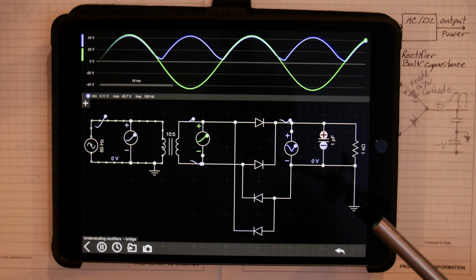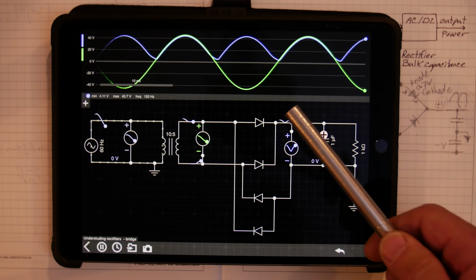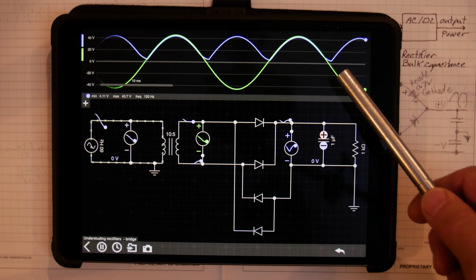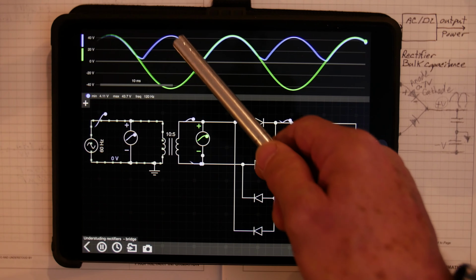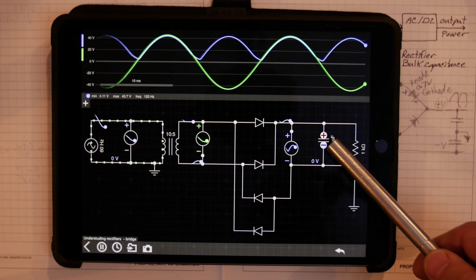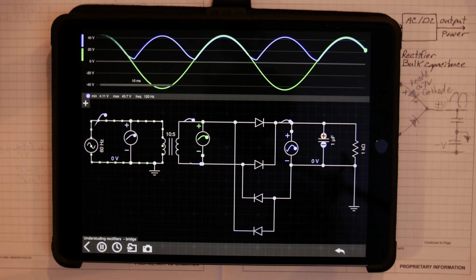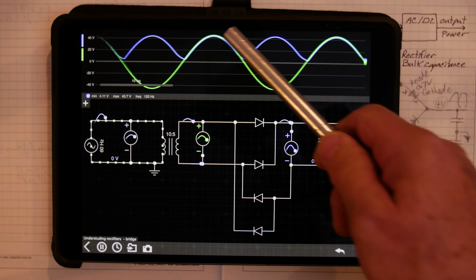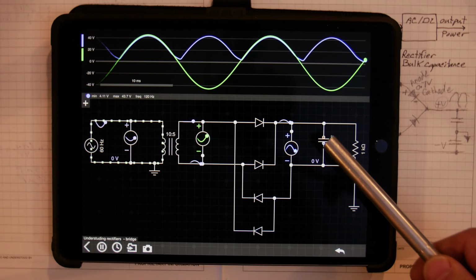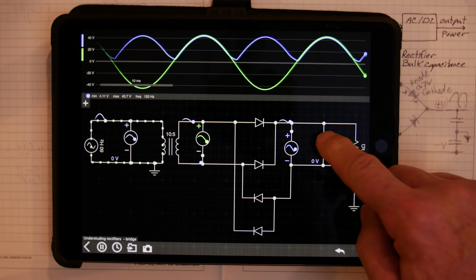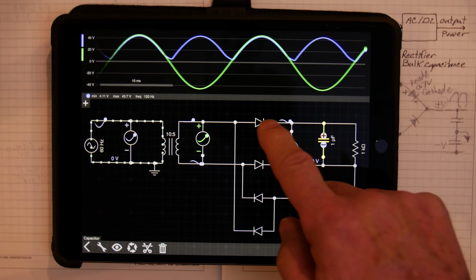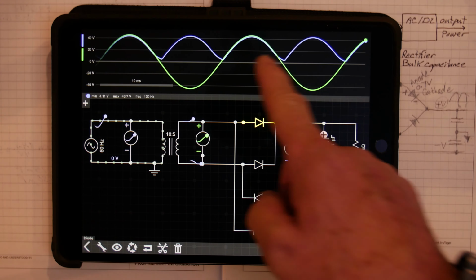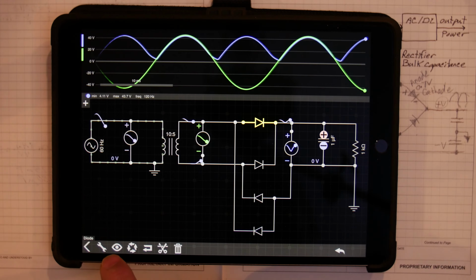So essentially we changed our waveform from 60 hertz to 120 hertz. Doubled the waveform, so we get double the charging pulses. And you notice on each trailing edge, it's a little bit of a bump like we got before with that 1 microfarad cap. Well, now you can imagine we don't need to have this capacitor as big because now the time between pulses is half. So let's start to make the capacitor larger. And by the way, let's watch the charge current. We're going to just look through one of the diodes because every diode is going to look the same. So we'll just look through this diode, okay?